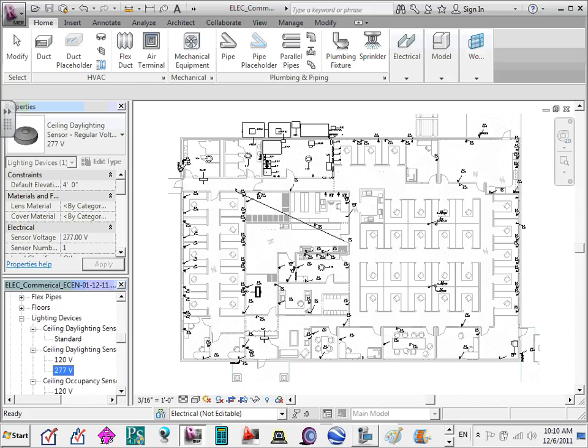So please, good. You edit the properties on these. Yes, you can. Thank you. Does it retrofit everything else, or does it just go from here forward? Yes, from here forward. Now, if you take this ceiling occupancy sensor, look what happened. I'm going to change the voltage to 277. What is... 277 to ground. No, you said you're going to change it to 208. Well, 120. I'm going to change it to 120. Make up your mind, Chad. I'm going to change to 120.